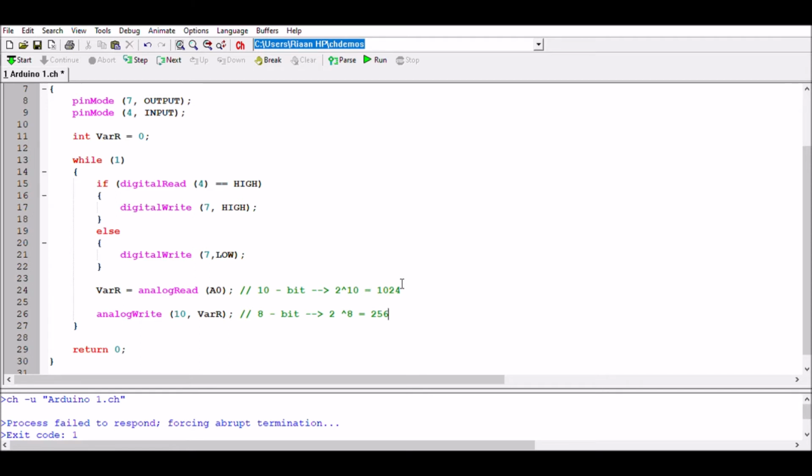And so we're able to see over here that's the reason why the cycle is happening. It gets to 256 or 255. As soon as it gets to 256, it drops down. It's an overflow that happens, and we see it going back to 0, and then it starts increasing again up to the next cycle where it gets up to 256, goes down again, and gets seen as being 0 again. So this overflow does happen.